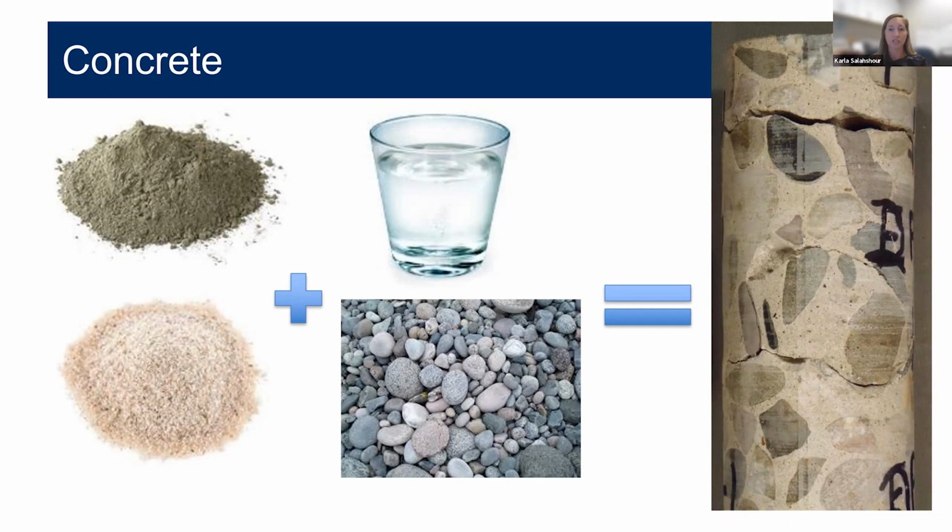So concrete traditionally has been a mixture of Portland cement, sand, stone, and water that when mixed together create this hardened material. Given that we're also discussing historic concrete, it's important to note that significant material changes have occurred throughout history. Some of the big advancements were grinding technologies, developments with kilns at the cement plants. A big one was air entrainment in the 30s, and many other advancements to admixtures in general. And so because of these developments, we've had changes in cement fineness and concrete mix proportions, water to cement ratio, placement methods, and many other things.